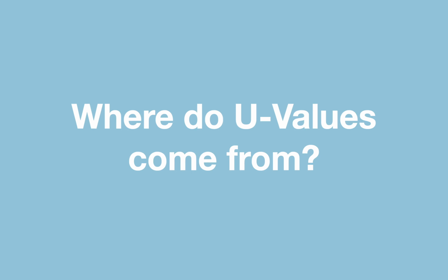It's obvious that U values are going to be really impactful on our passive house. The level of insulation is going to be one of the key drivers of the overall building's performance level in a cold climate like New York. So we know that they're going to be really critical. We also know that the PHPP is not going to be able to do its work without these U values. So the U values are going to be absolutely central to the primary function of the PHPP, calculating heat transfer through all of the various surfaces.